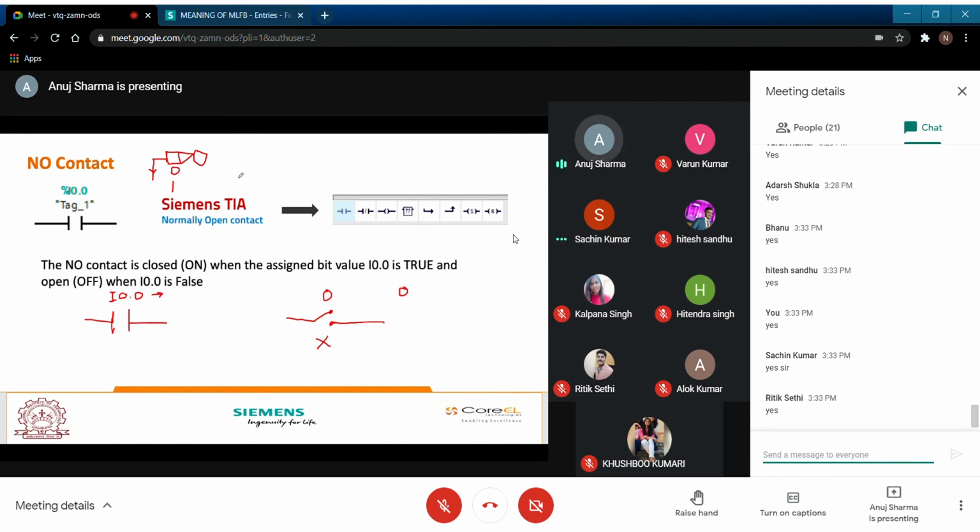Okay, so for a condition when there is no material associated with your sensor, we have looked at the diffusion sensor. When there is no material, the rays will not fall back through diffusion, and the state will be 0. And when the material is present, the rays will fall back to the sensor and a current will flow, and the state will be 1.